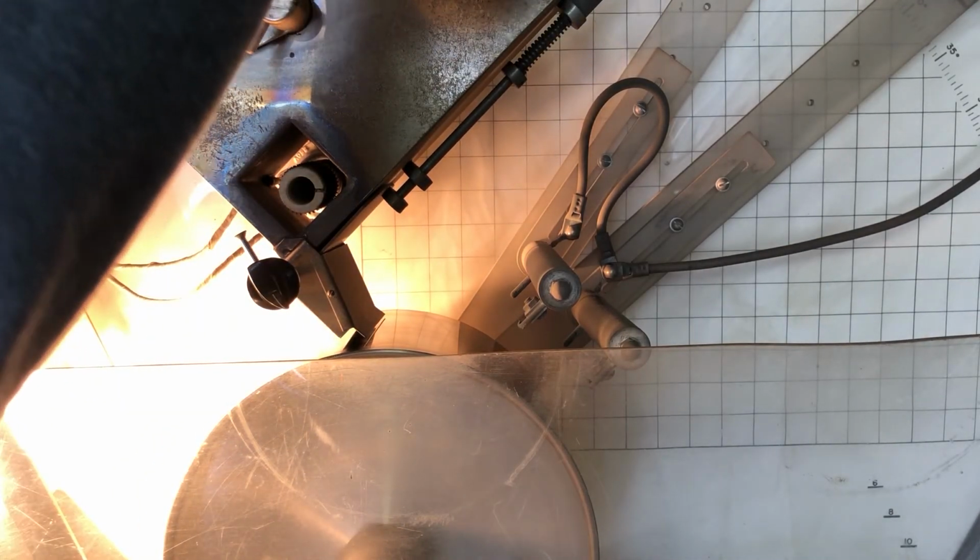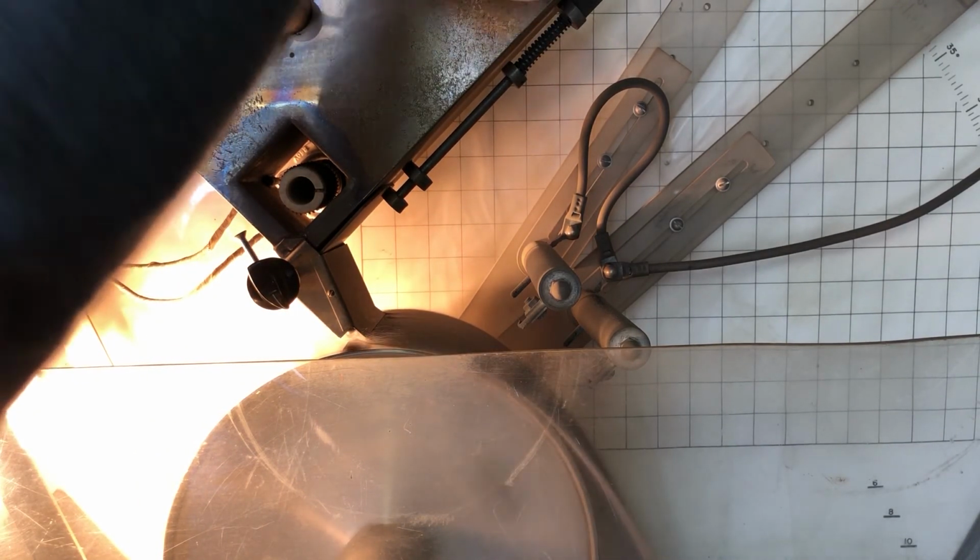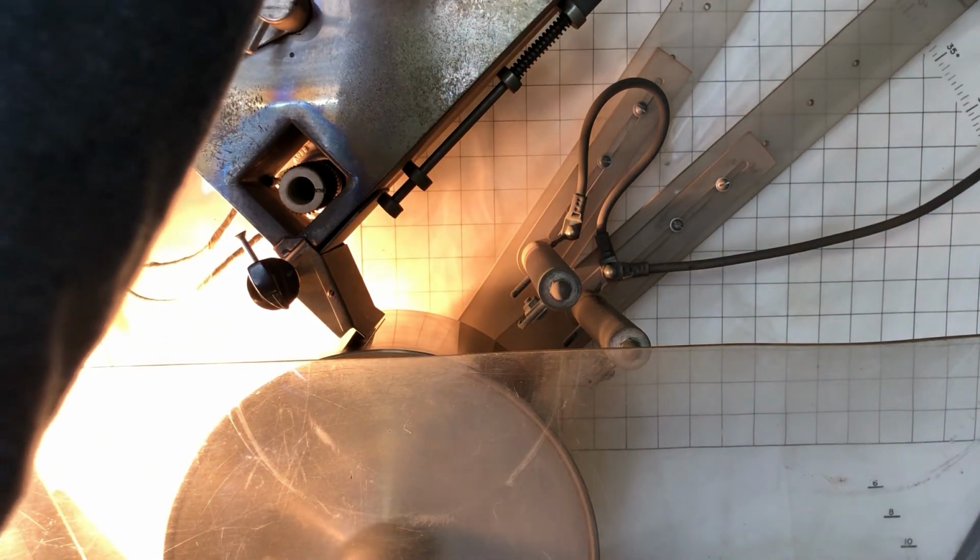The first step I'm going to take is to reduce the amount of feed going onto the rotor to make a better separation. In a real process plant, however, one has to calculate if a reduction in feed rate and therefore production rate is economically viable.